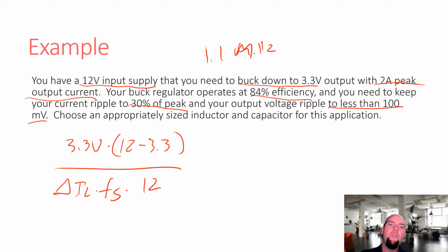So if you're switching too quickly, you're going to spend almost all your time in these transition events where you're opening or closing your transistor. And those are the bad ones. Those are inefficient. You don't want to be doing that a lot. So they'll generally slow it down to drive the gates of a bigger transistor for high power applications, and it means you need bigger inductors and capacitors. But for normal current applications, 1.1 megahertz is very reasonable.